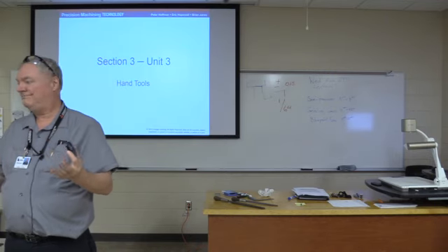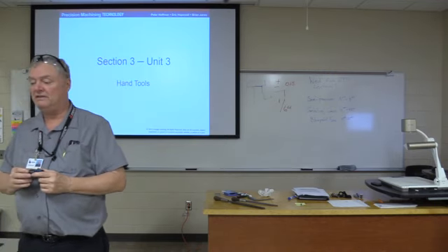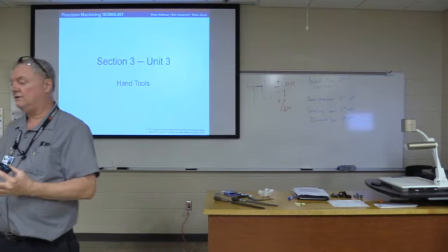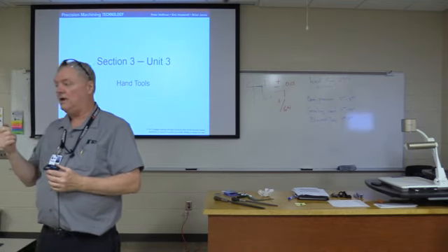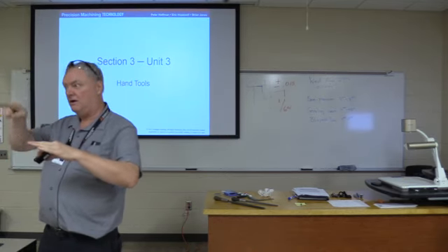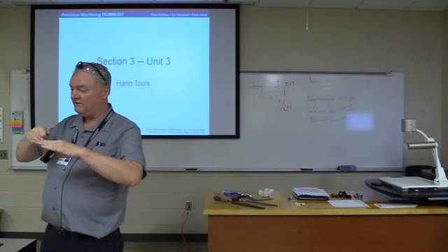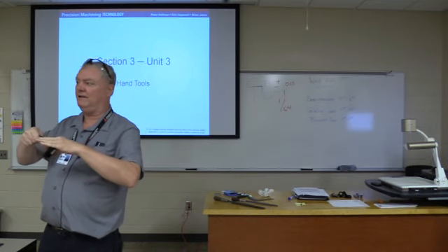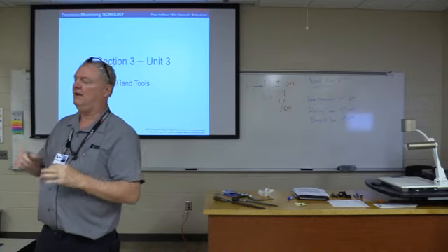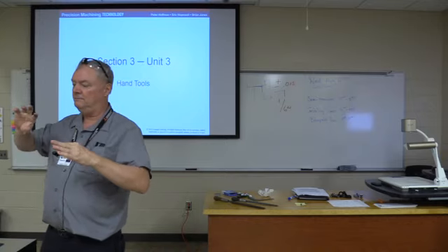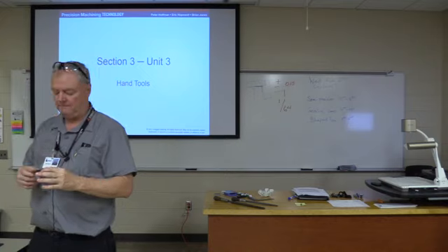In many shops, there's always a need for the skill of understanding how to take a round file and open up a bore. That's a very precise, accurate hole, and you might have to do what they call lapping, a very fine bit of filing to open it up so that a pinion can go through it, for example.